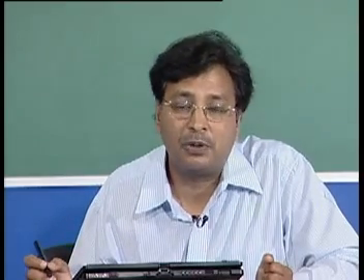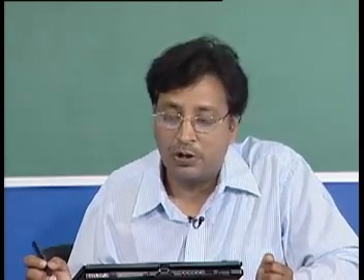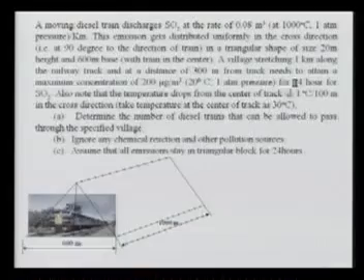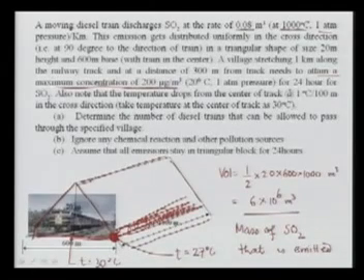If you recall, our concentration is changing because the meter cube is changing. The 1 meter cube is different. If I go back to the slide, you see the 1 meter cube at this point and 1 meter cube at this point, they are all different because the temperature is changing. So this meter cube here, here and here is not the same. So I must change this meter cube to the conditions at 27 degree Celsius.